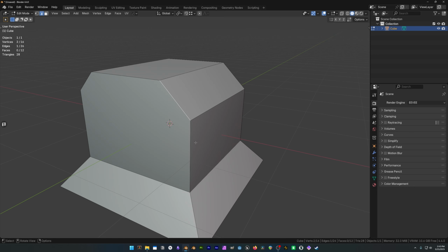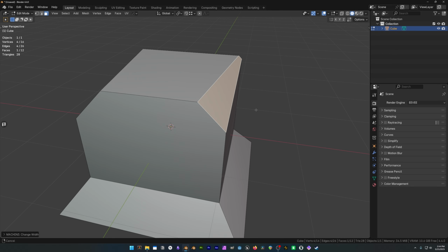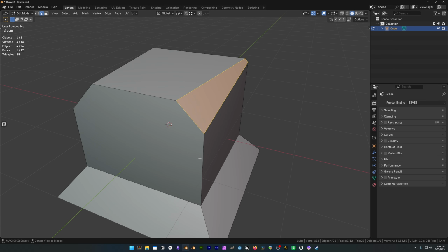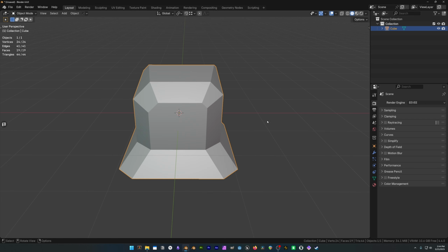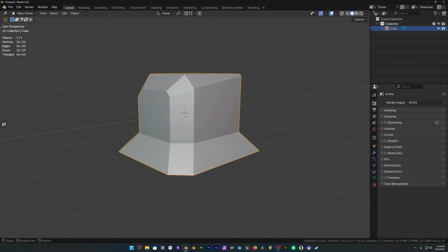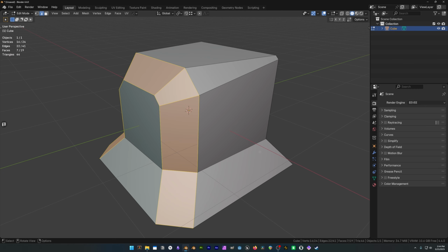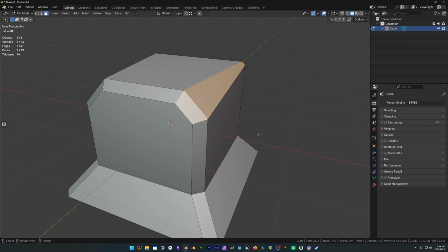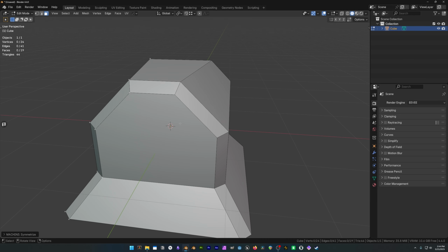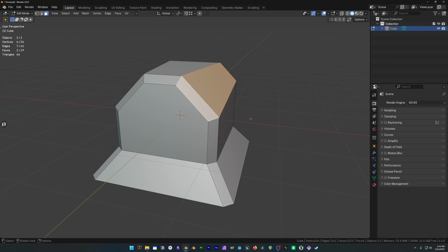And so with machine tools, being able to adjust the bevel width is so crucial in game design. Non-destructively edit and make bevels. I don't have to worry about making bevels on an asset with this add-on. It's so much better. I can do crazy stuff like this and block out the asset and then be like, oh, actually, I don't want this huge bevel, or this would look a lot better if it was bigger.